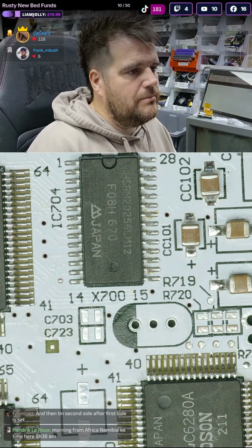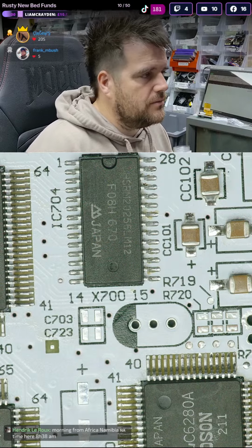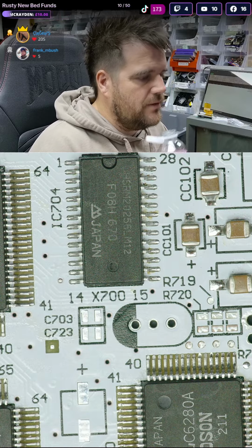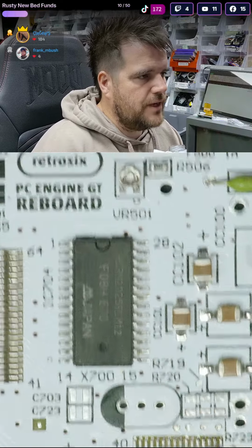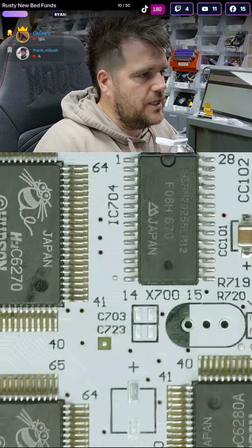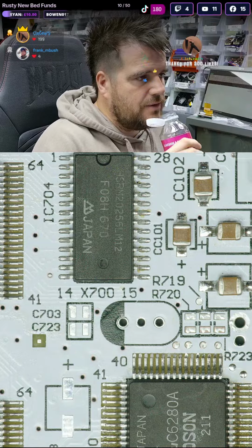The hot air will melt both sides evenly, let the flux and solder flow and the component fly into position. So it's a much cleaner way of getting them to naturally pull into position. You saw how these pulled in and the fillets are perfect. You wouldn't do that with a soldering iron unless you're a lot more skilled. Whereas with hot air you don't need to be that skilled to get that finish.